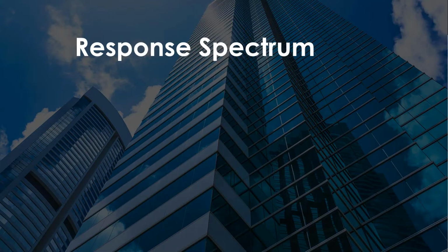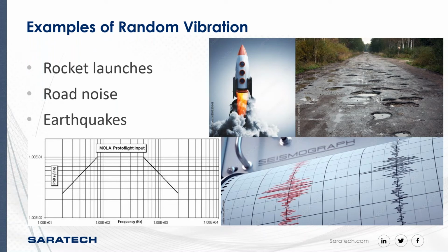Situations in which we might want to use random vibration would be a rocket. Rockets generate a lot of energy and have a lot of moving parts. Well, not necessarily moving parts, but there's a lot of parts generating movement. And these overlapping signals will cause the input signals to be too noisy, and so therefore we'll take more of a statistical approach to it. Also turbulence, anything like that, those are irregular, so they are usually taken in a statistical format. Same thing with road noise for an automobile cruising along a very pothole-ridden road like this.